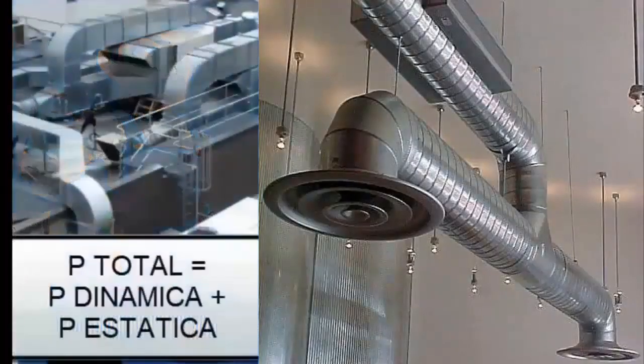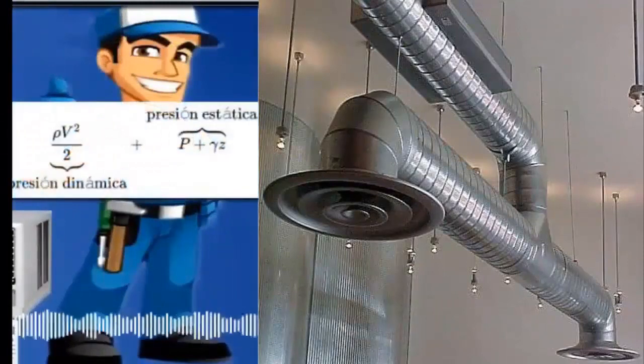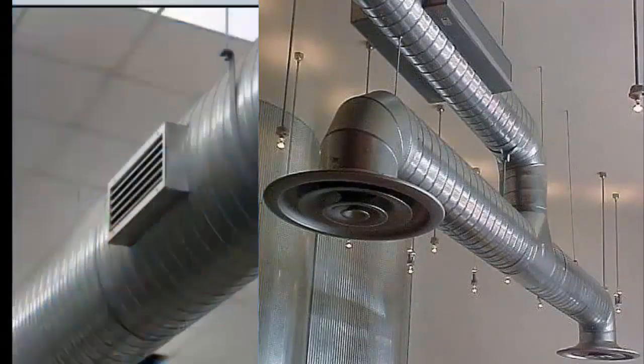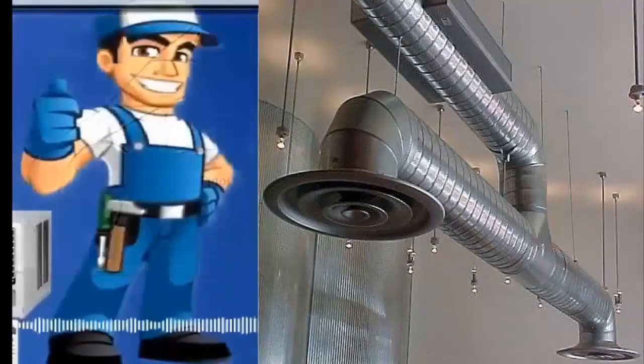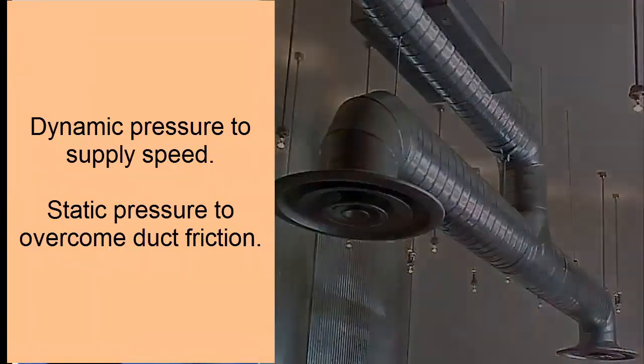The duct system fan delivers two types of pressure, dynamic and static pressure. Note 9. The sum of both pressures represents the total energy that the fan delivers to the air. Note 10. The static pressure, for example, measured in millimeters of water column, is the pressure necessary to overcome the friction of the air with the walls of the duct, and it must be supplied by the fan in order to get the air to all the grills. Note 11. The dynamic pressure has to do with the speed that the air carries inside the system, and also depends on the flow rate and the area of the ducts.